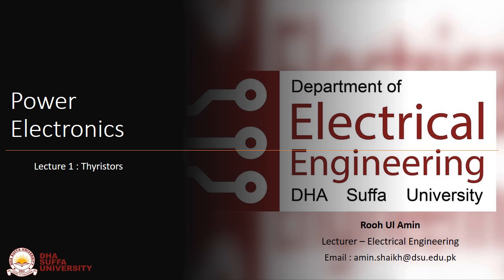Well, power electronics actually deals with the applications of solid-state devices for the control, conversion, and processing of electrical power. Conversion techniques require switching, which means on and off of power semiconductor devices. I already told you that the basic elements which make up the power electronics are called power converters, and power converters are actually used as interfaces to match the supply characteristics to the load characteristics. This is the basic aim of power electronics.